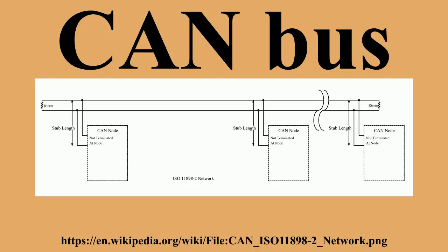In those scenarios, a low CAN bus utilization of circa 30% was commonly required to ensure that all messages would meet their deadlines. However, if IDs are instead determined based on the deadline of the message, the lower the numerical ID and hence the higher the message priority, then bus utilizations of 70 to 80% can typically be achieved before any message deadlines are missed.